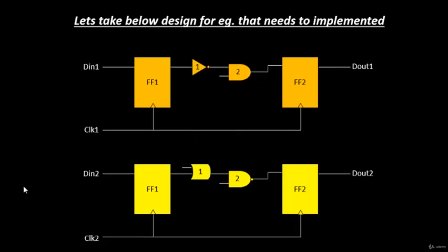Along with that we have some pre-placed cells as well. We have done the placement of some IPs in the previous section, so these are those pre-placed cells. We have this block A, which has some connectivity like this. It receives its first input from the D in 1 port and its second input from D in 2, and the output goes to one of the inputs of the combinational gates. This is just a circuitry to explain the concept of placement and routing.